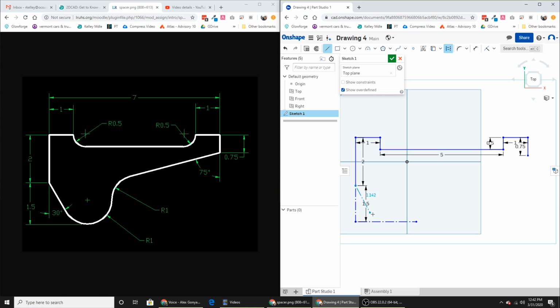I'm going to click here and click here. Now you'll notice anywhere along this line I get little symbols telling me that it's touching the line, and it's either coincident or it's at a midpoint. I saw a midpoint there somewhere. There's a midpoint. None of those are necessarily what we're looking for, but the coincident will help us out. It'll at least let us know that the line, the 30-degree line, is touching this other line. So I'm going to stop drawing at that point.